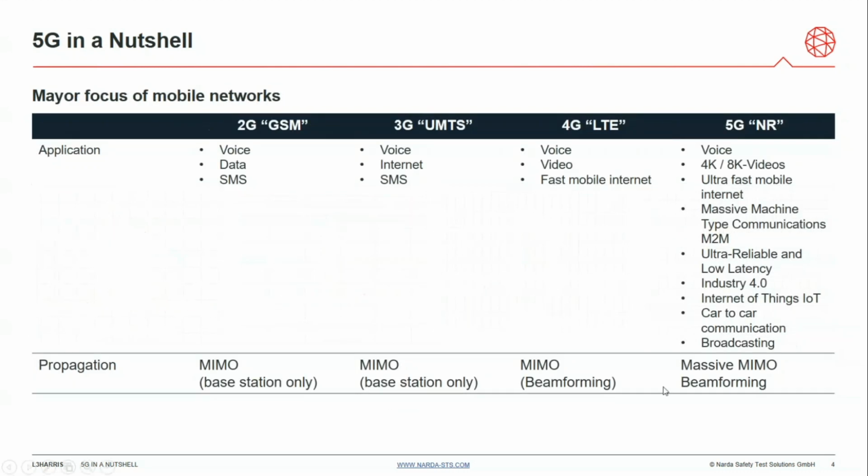machines. The last line maybe is important, that the propagation or the transmission of the signal was in the past mainly SISO, single input, single output. We have seen a few MIMO. So with 2G, there was already co- and cross-polarized antennas, dipole antennas with 90 degrees in between their two propagation lanes. With LTE already, few of the latest LTE implementations we have seen already beamforming, and with 5G now there's massive MIMO, and beamforming will be probably the standard implementation.